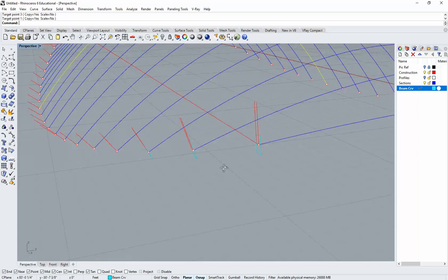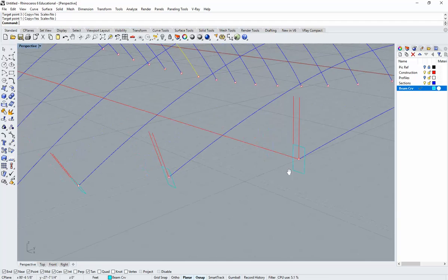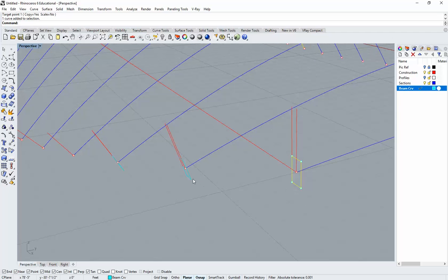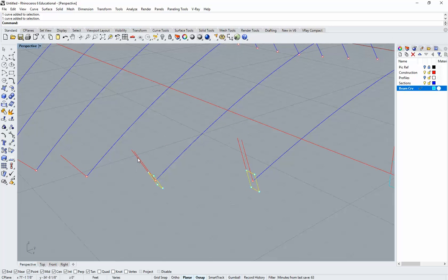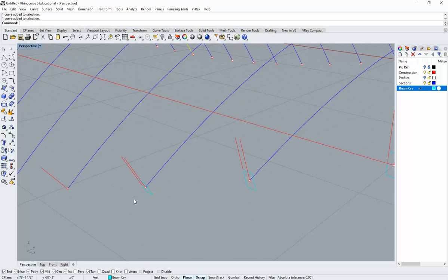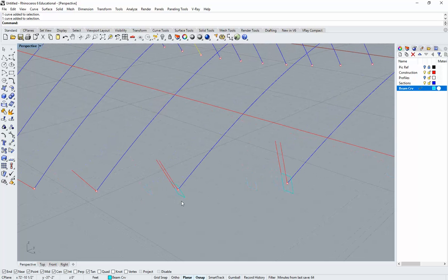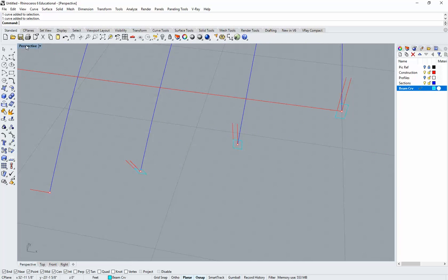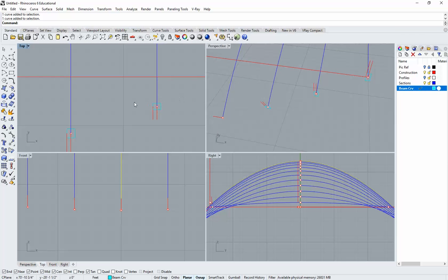Anyway, what we've done using that command and the offset is orient each one of these parallel with those lines that we drew earlier that were perpendicular to our section curves. If that seems like a little bit of extra work, you'd probably be right, especially since if we go to the top view, those sections are actually straight on. They're orthogonal to the x-axis, and that's what we wanted. That makes our lives a little bit easier. If these were oriented with a bit more of a rotation along the z-axis, we'd probably really need to use that command.